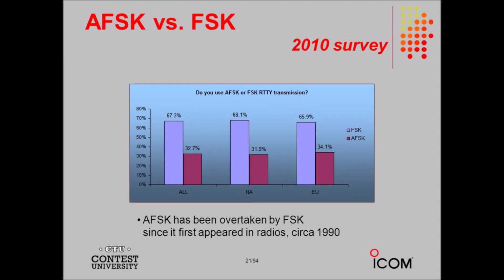These amplifiers generally work in Class A except for the PA, which operates in Class AB or Class B. We'll never see a Class C amplifier as the PA in an SSB transmitter because Class C operation distorts any signal whose amplitude varies over a continuous range.